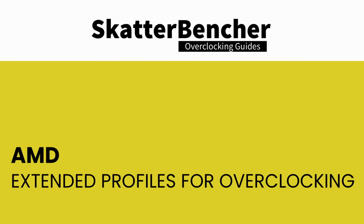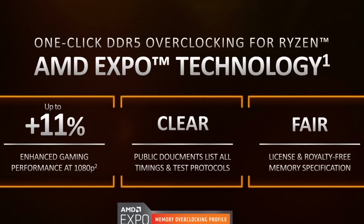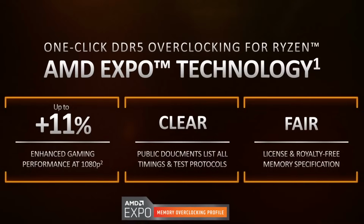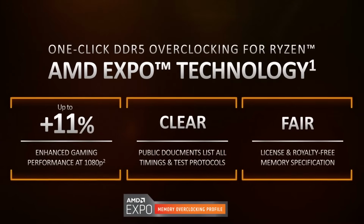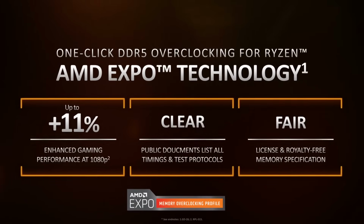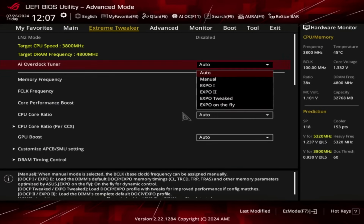EXPO stands for AMD Extended Profiles for Overclocking. It's an AMD technology that enables ubiquitous memory overclocking for AMD platforms supporting DDR5 memory. EXPO allows memory vendors such as G.Skill to program higher performance settings onto the memory sticks. If your motherboard supports EXPO, you can enable higher performance with a single BIOS setting. So it saves you from a lot of manual configuration.